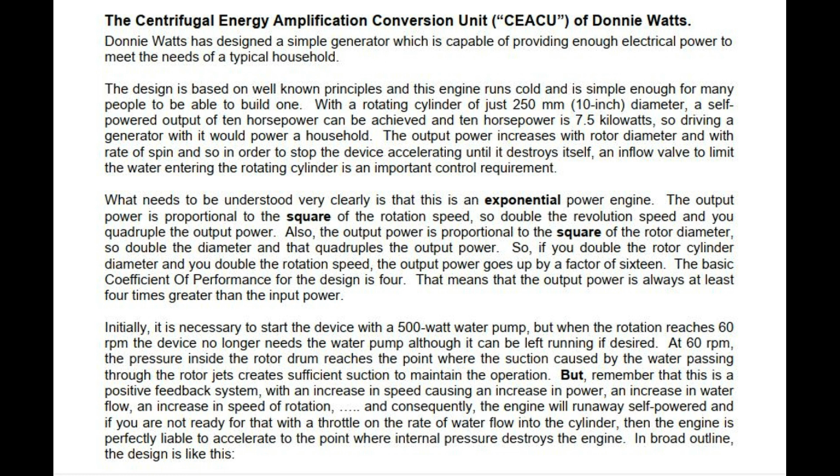With a rotating cylinder of just 250 mm, 10-inch, diameter, a self-powered output of 10 horsepower can be achieved, and 10 horsepower is 7.5 kilowatts, so driving a generator with it would power a household. The output power increases with rotor diameter and with rate of spin, and so in order to stop the device accelerating until it destroys itself, an inflow valve to limit the water entering the rotating cylinder is an important control requirement. What needs to be understood very clearly is that this is an exponential power engine.